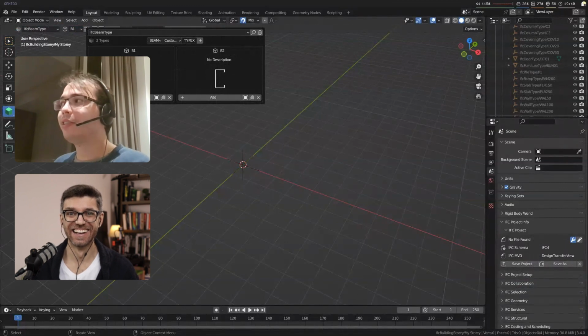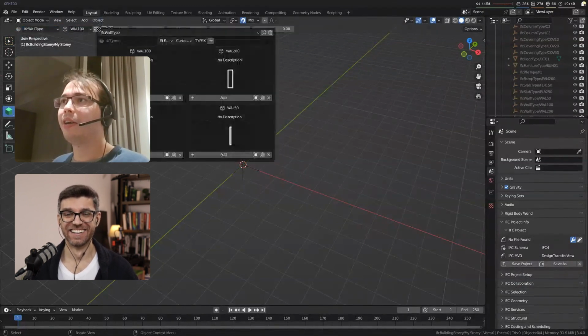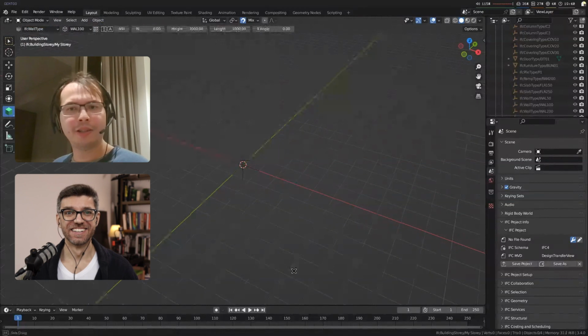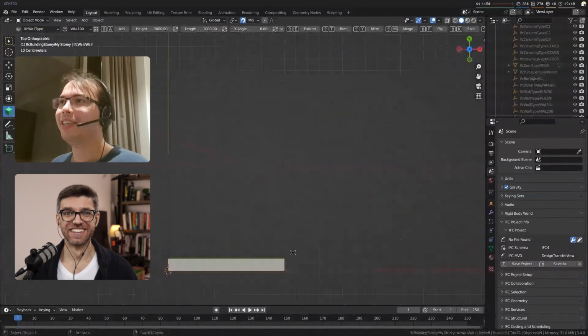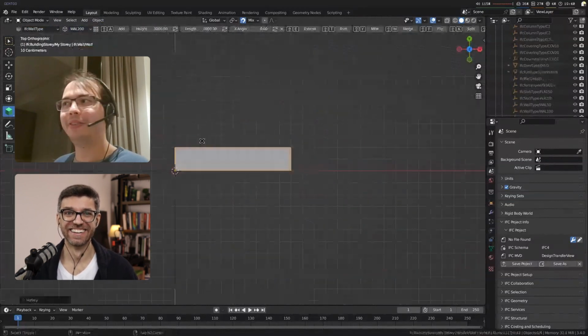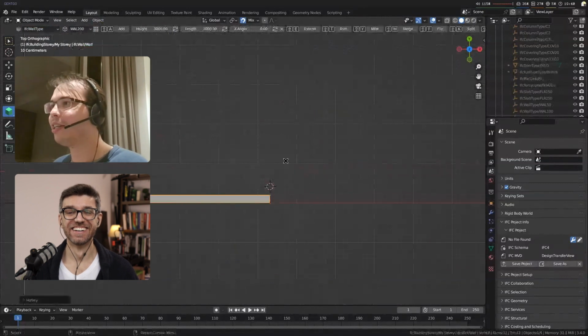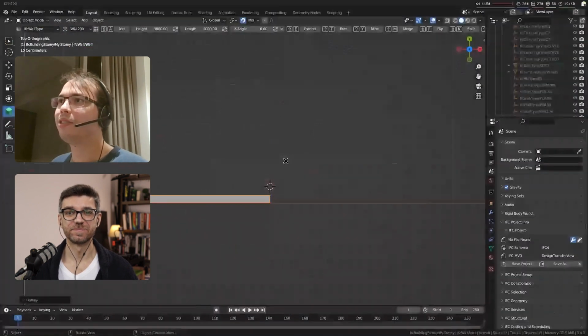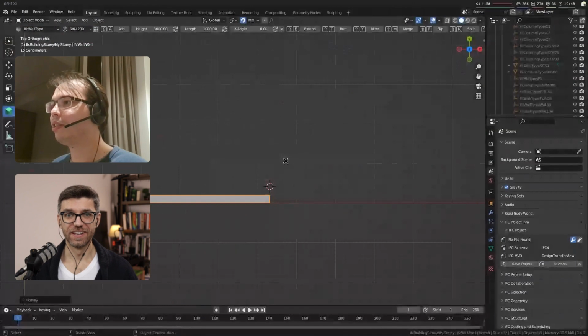It comes with a bunch of assets, which you see here. So I've got a few beam types over here. That's all you need to build a house, right? Just those two beams. You need walls. I've got a 50 millimeter wall. Anyway, so let's start with some nice exterior walls, 200 thick.